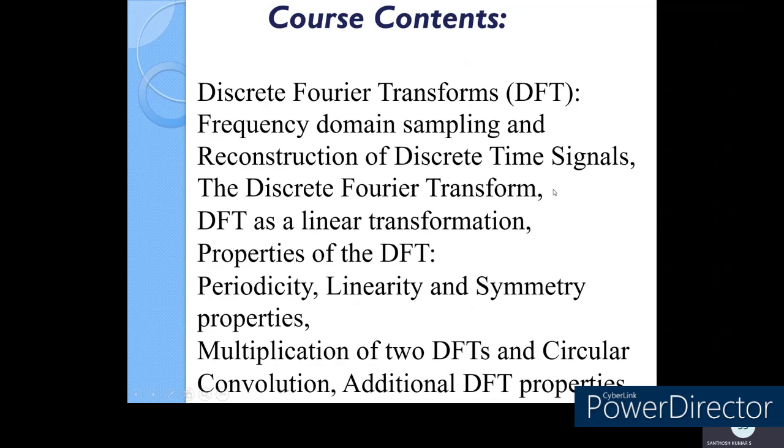In the frequency domain, you are going to get a periodic spectrum. That periodic spectrum is continuous with respect to frequency, but it is not discrete. So in the time domain it is discrete, but in the frequency domain it is continuous, and it is also periodic. But for signal processing, where we use a digital computer or a digital signal processor, in order to perform operations the signal should be discrete in the time domain, and in the frequency domain also it should be discrete. So the DTFT is not an efficient tool for performing operations by a DSP processor or computers.